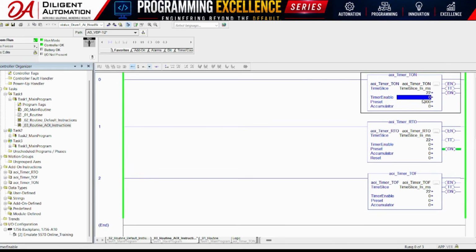As you can see, the operating principle is exactly the same as the built-in TON instruction. The difference is that we've implemented the logic ourselves using an add-on instruction. By developing this instruction from scratch, we're not just learning how to use a timer, we're learning how timer instructions are actually designed internally. This understanding will help you create your own reusable add-on instructions and write more robust, maintainable PLC programs. Now that we've understood the TON add-on instruction, let's move on to the retentive timer on, RTO, add-on instruction.